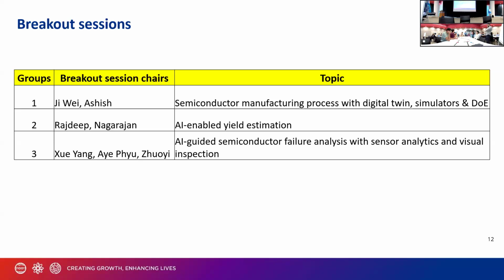Right now, we can stop the further process if we see something is wrong with the chip, because we get the data and we can save the assembly cost and the follow-up test cost. And in the worst case, we can take one piece of wafer to do a sample study and showcase. So that is what we call full attack.